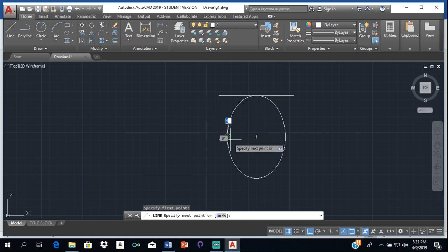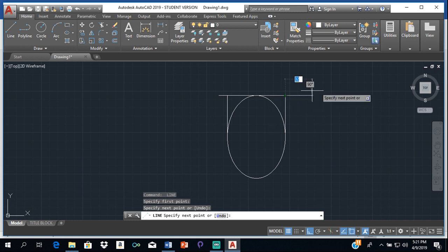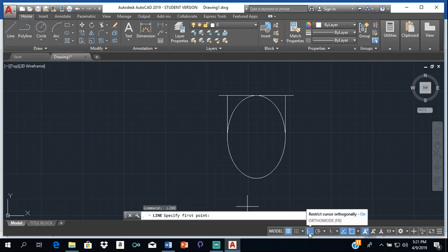So you just click down here, bring your mouse up, and you will see this right here once you have perpendicular turned on. So you click there, then you press space bar again to get back the line. Click on this quadrant and bring this line up right here. Alright, good. Also now we're going to select line again, but this time we're going to turn off ortho because